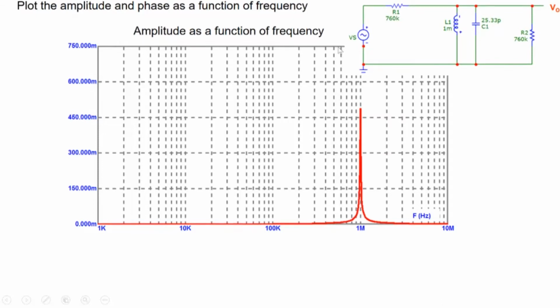So you note that if you think of it as you have a sinusoid as an input, this sinusoid is trying to go through this particular circuit and emerge at the output. So what the circuit is doing is severely attenuating 1 kilohertz, 10 kilohertz, 100 kilohertz. It's not allowing those signals to pass through, right? The amplitude of V naught is very small. Similarly, high frequency signals are also, if I were to do it at 100 megahertz, that also would have come out to be close to zero, a small value here. So similarly, high frequency signals are also being filtered out.